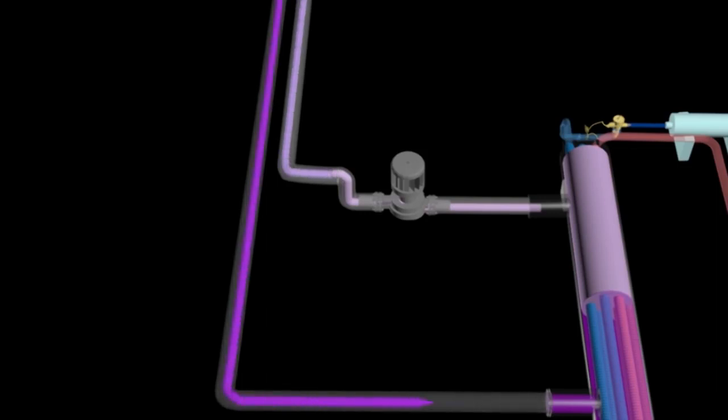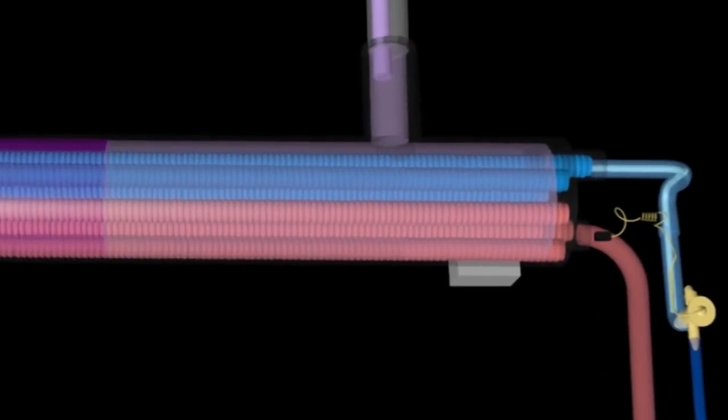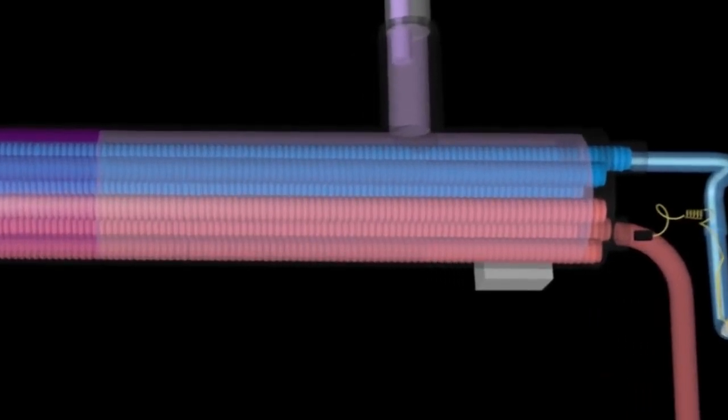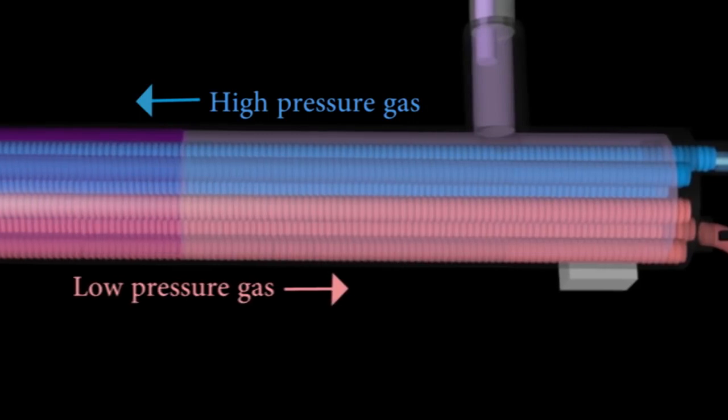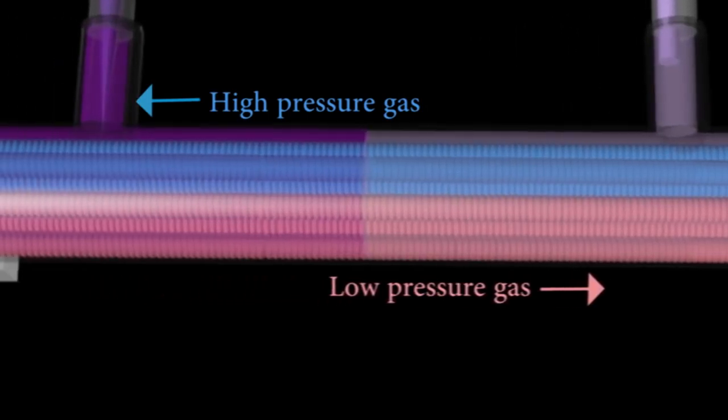When the liquid refrigerant with low temperature and pressure absorbs heat from the chilled water, the refrigerant will evaporate to low-pressure gas. The evaporator most commonly used is shell and tube type, where the refrigerant flows in the tube and the water floods the shell.